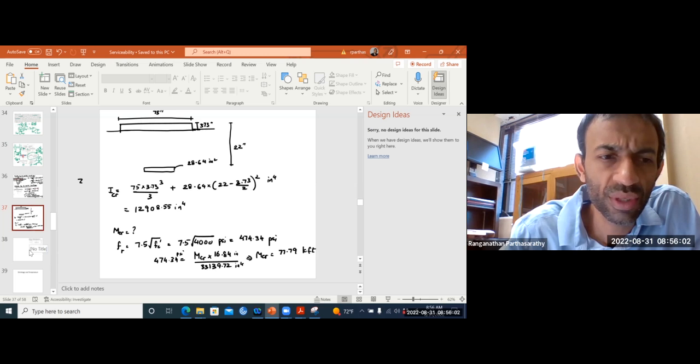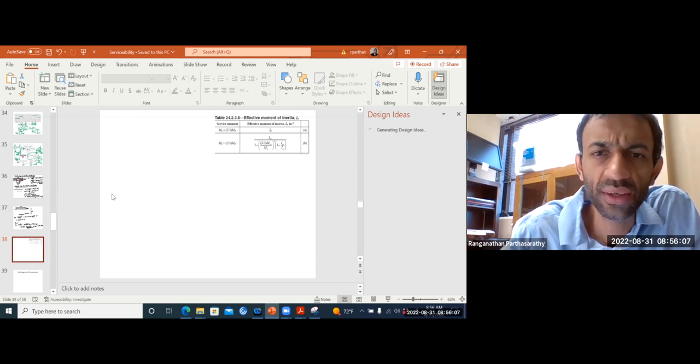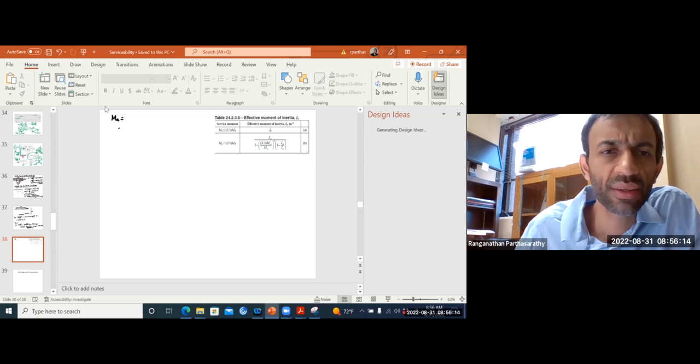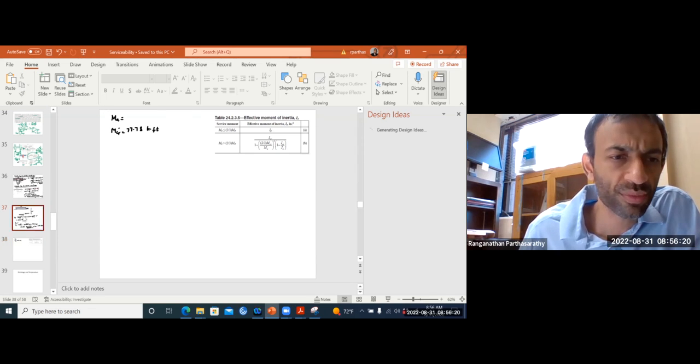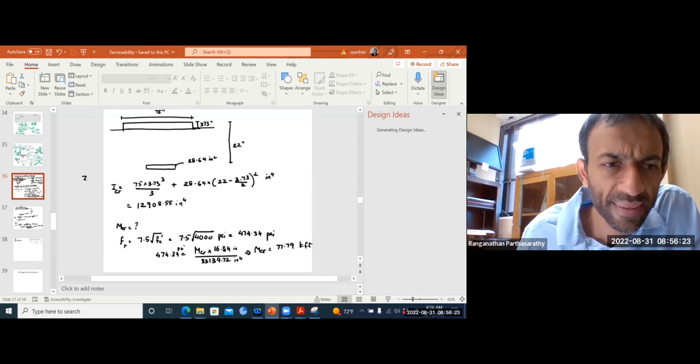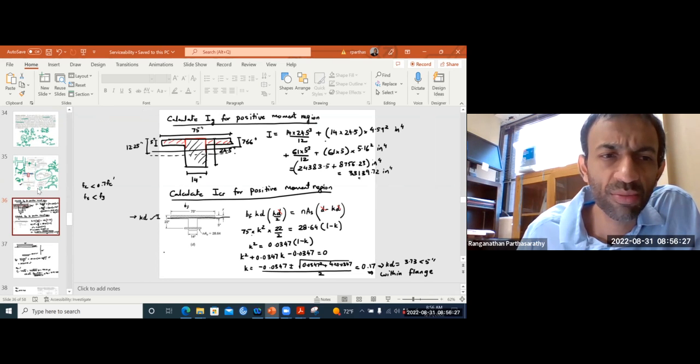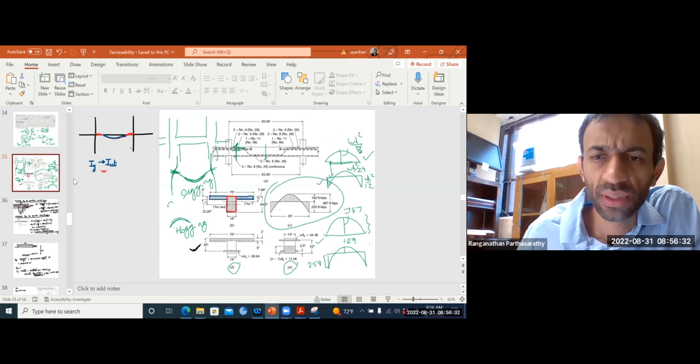Let's use your MCR and your MA. The MCR we just got, 77.78 kip foot, and your MA, M applied, we take it in the positive moment region as 162 kip foot.